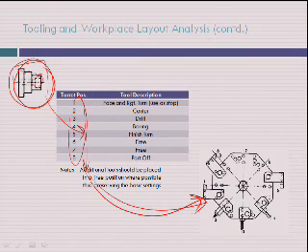The point again is that production flow analysis, a method thought about by Professor Burbidge 50-60 years ago, actually has a very flexible structure. What it says is, go into any workflow system, look at the objects which are being used in the workflow system, look at all the workflow patterns, map those patterns in terms of the sequences in which those objects will be used, and then using appropriate additional data, including a layout of the system, wow, you could re-engineer the workflow system.